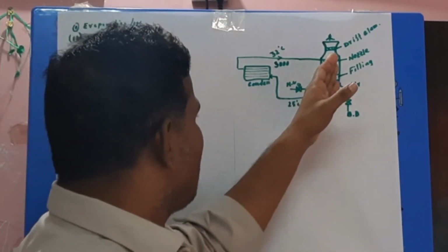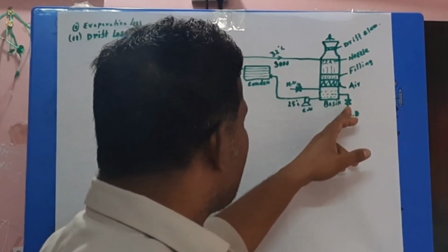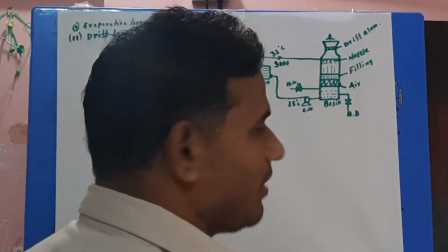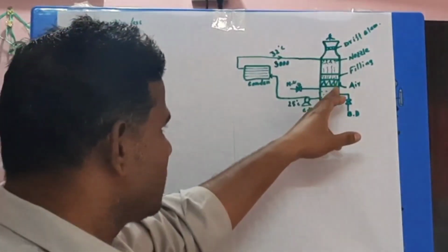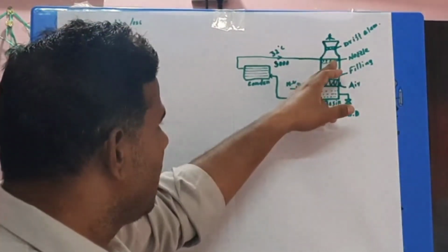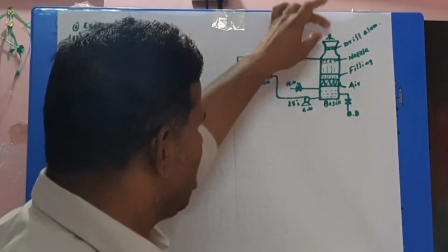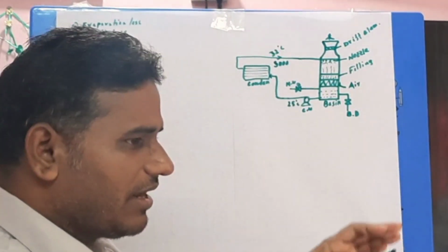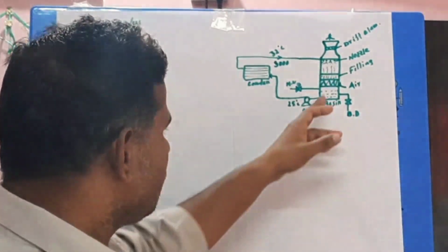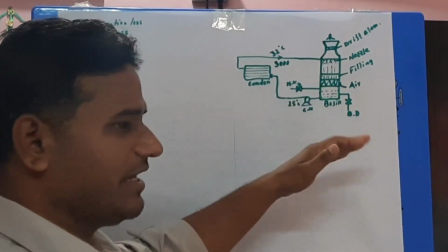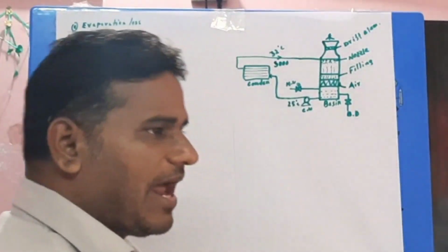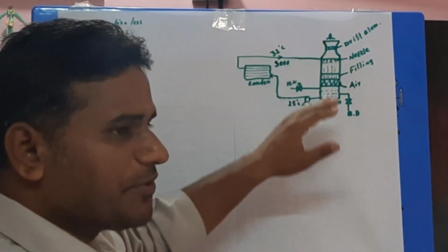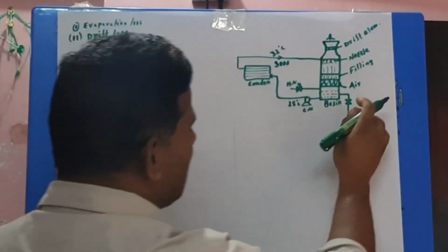Another loss also happens in the cooling tower. This loss is blow down loss. So why is this blow down required? I will explain one by one. Normally, impurities are also available in this water. When pure water evaporates and the impurities are added again to the basin, what will happen here? The impurities will increase. If the impurities increase and this water is provided to the plant, the tubes or lines will be damaged. For controlling the impurities, we do this blow down.